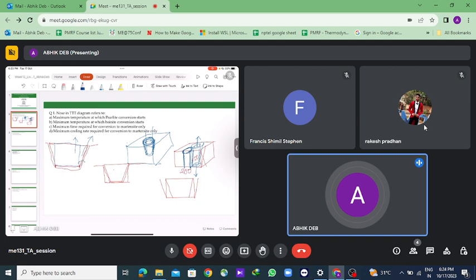If you are providing the draft like this, we will have the same issue as before. I mean, if you are giving the inside cavity bigger, then there will be some portion inside that has to be chipped off, isn't it? We need to remove it through the machine, isn't it?